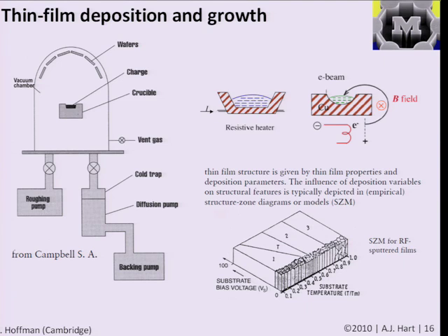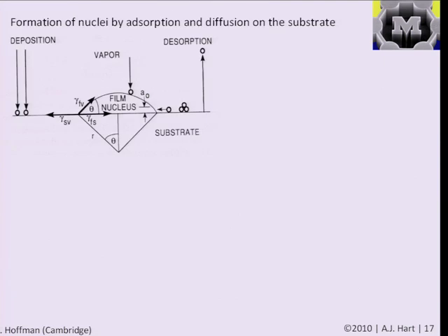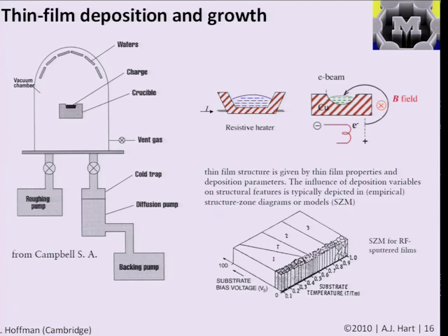But when we think about synthesis at the nanoscale, we want to think about specifically how the atoms that come from this precursor phase deposit on the substrate and form the initial nuclei of the surface. And if we go for a long time, we might get one of the types of thicker films that we schematically saw here. But if we control the process for a short time, we might make these isolated small islands that can be considered nanostructures and then can be quantum dots on the surface, or can be catalysts or sites for growth of subsequent structures.